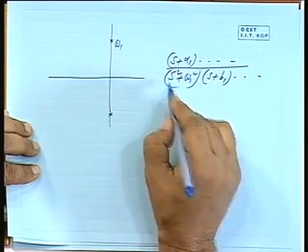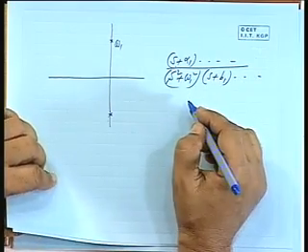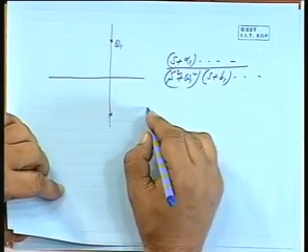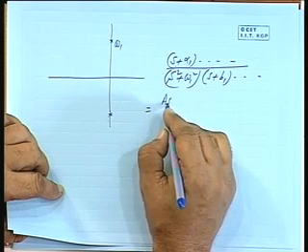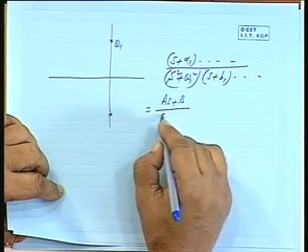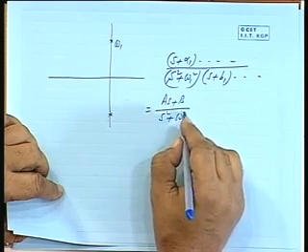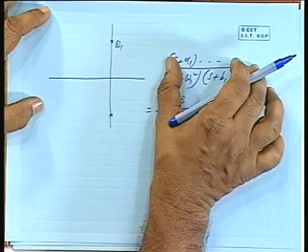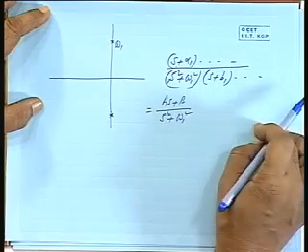One factor is say S squared plus omega 1 squared. This will result in a term like sum AS plus B by S squared plus omega 1 squared. Okay. Once again you apply an impulse. If you apply an impulse of voltage, and if this is the admittance function, voltage into admittance will give you the current.